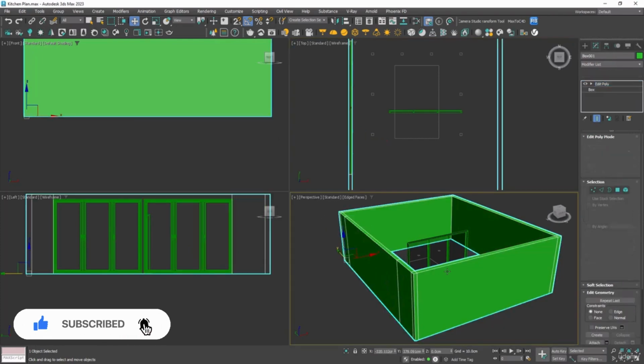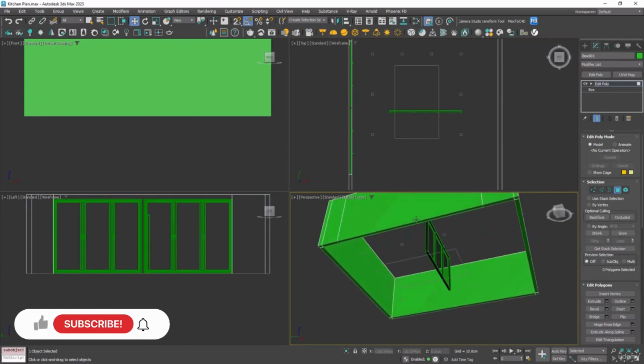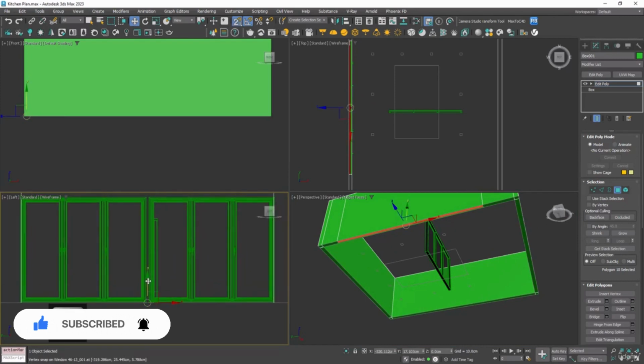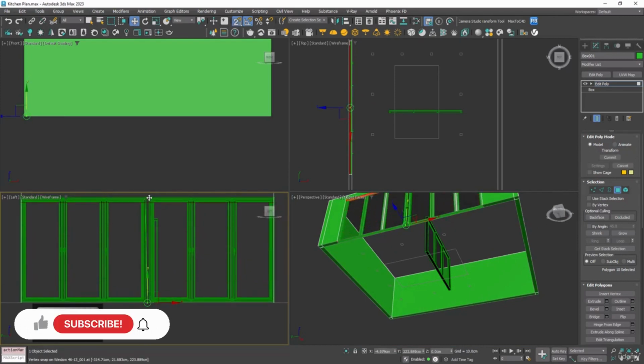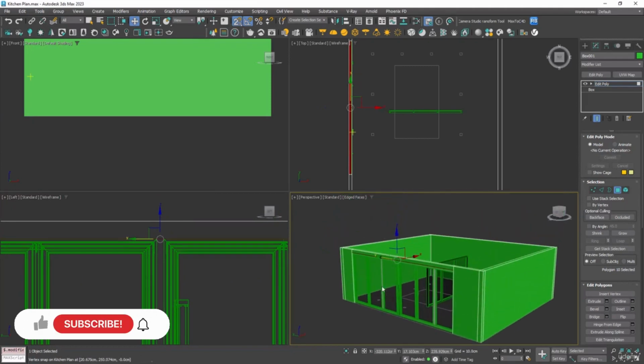And then we can select our walls again, and we want to select the face underneath our doors. And then in the left view, make sure snaps is on by pressing F, and holding Shift, we can snap that to the top of our doors. And you can see back in perspective, that's made easy work of lining our doors up.